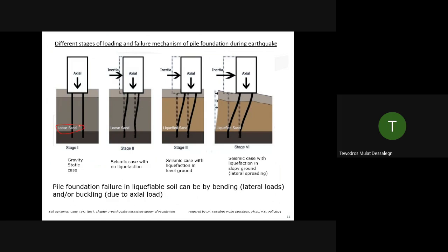And in loose sand, you say, oh, I may have liquefaction, so I'm not going to do any shallow foundation. Especially isolated foundation is the worst one. Mat is better. At least the whole thing can survive together. But differential settlement-wise, the isolated foundation is the worst one.